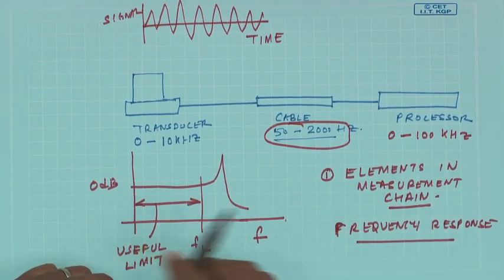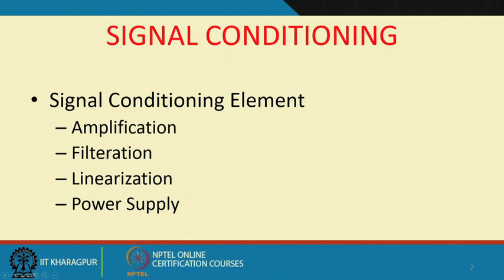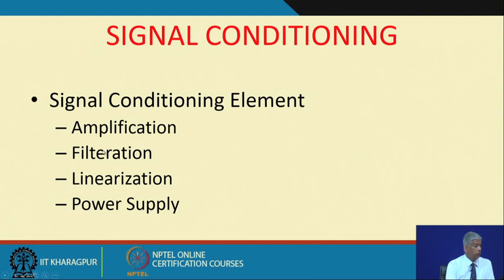So, if you will see a signal conditioner, we need to have good settings on the filters. All these filters may not be available in a single signal conditioner, but definitely a low pass or a high pass filter is there, and sometimes a notch filter is there. I mentioned octave band filters; that is just from post processing, where some octave band analysis could be done.